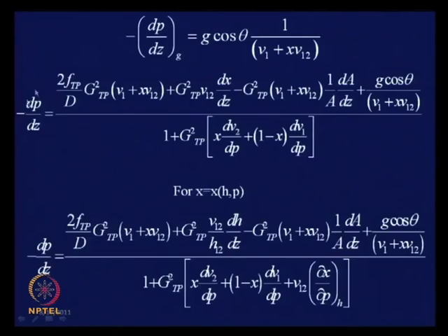Well, the other thing which I had mentioned in the last class was that, apart from discussing the significance of the denominator term, in the expression of momentum which is already present, the only term which we do not know is the two phase friction factor, f_TP. This is the term, and I think we had started discussion on the different methods of finding out f_TP.